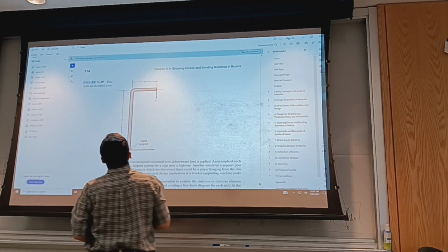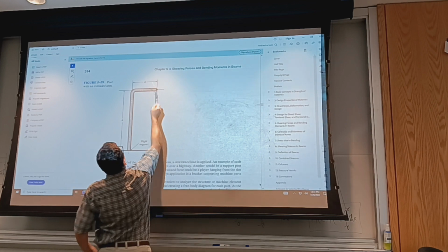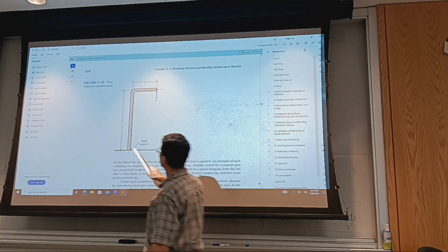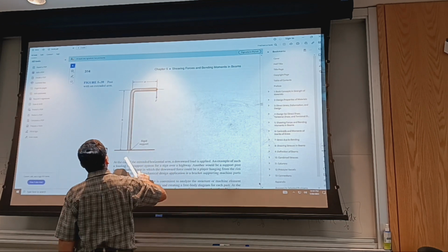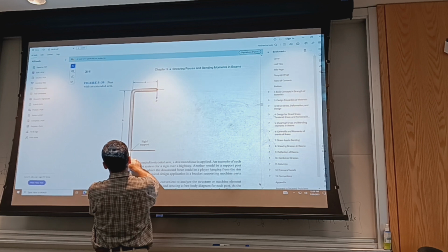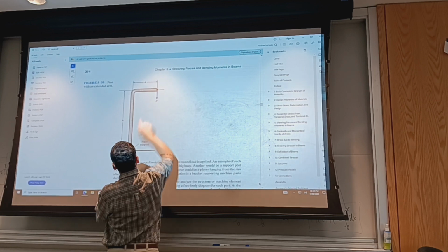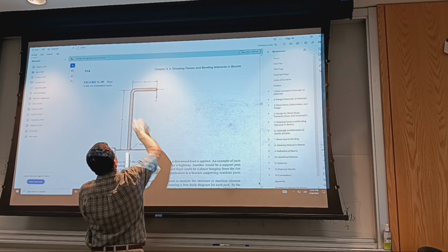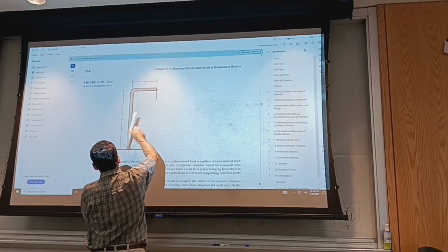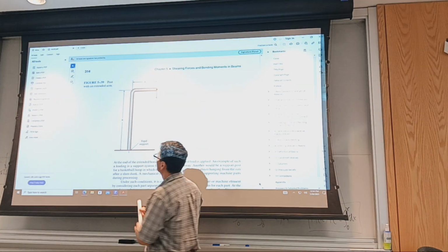And what is the method of doing it? You isolate first. You go from the load to the support. So we can find the reaction at the support, which will be F pointing up, and then, because this has a tendency to rotate, I need to show a moment. This is like having a fixed support.